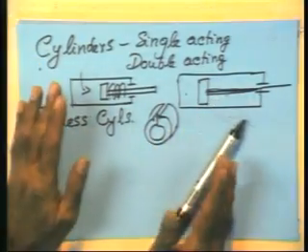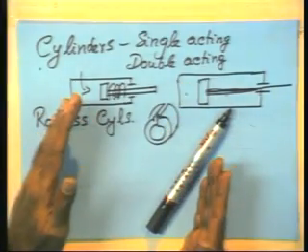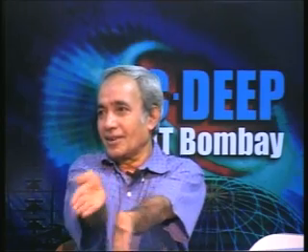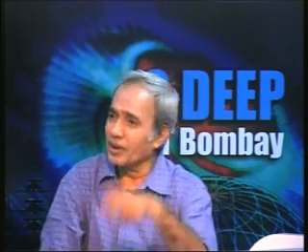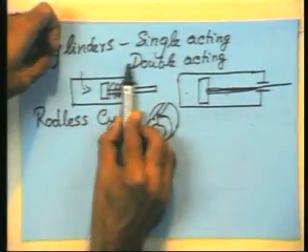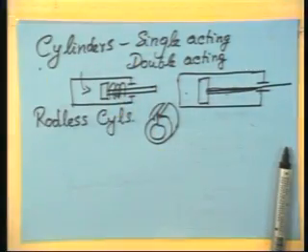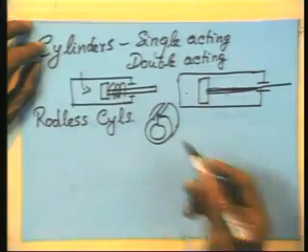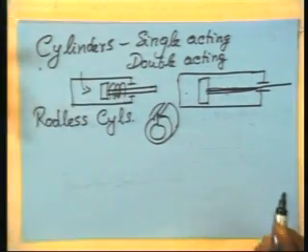and down. Along this length, in order to seal the air in, there are flaps which close like this, magnetic, and seal the air. These are rodless cylinders. Mostly they are used in pneumatics. So there is no piston sticking out. The whole thing moves this way and that way. You can look up the web, and you will see pictures. Many people use them, but there is leakage here and those problems are there.